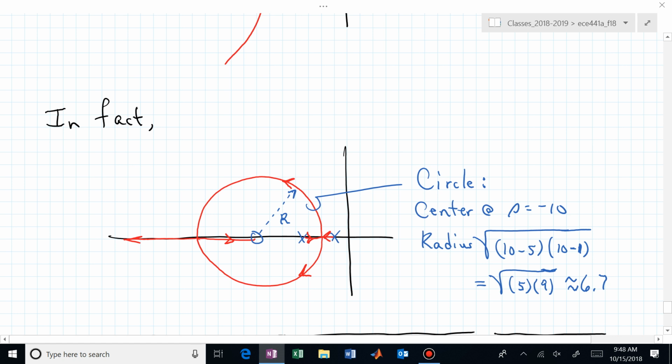Here we have 2 poles, so the triangles live on those red lines. That's the root locus for this particular system. This is the only place that you could possibly live with your closed loop poles for that particular system if you're using just a scalar gain K. If you haven't introduced any other controller except a gain adjustment, now you can live on that set of red lines, which really is 2 branches of the root locus.